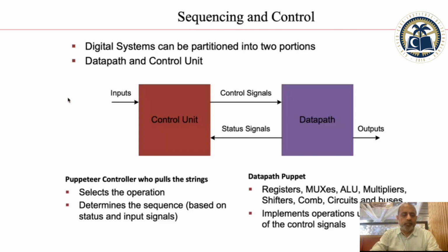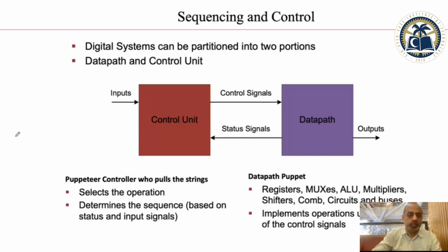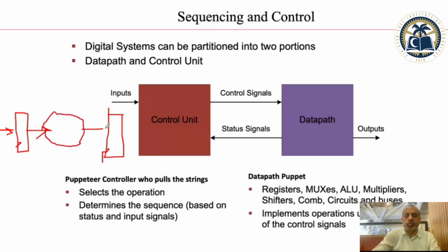So that's why we have been stressing that once we talk about digital design at a high level of abstraction, the only thing we need to know is where your registers are. It is very important to understand that register transfer level means you have to be aware of all the registers in your design, and the logic in between two registers is the combinational logic. This combinational logic is based on actual transistors, meaning gates are built of transistors. So a signal is going to take some time going through this cloud, because every transistor is going to add delay.